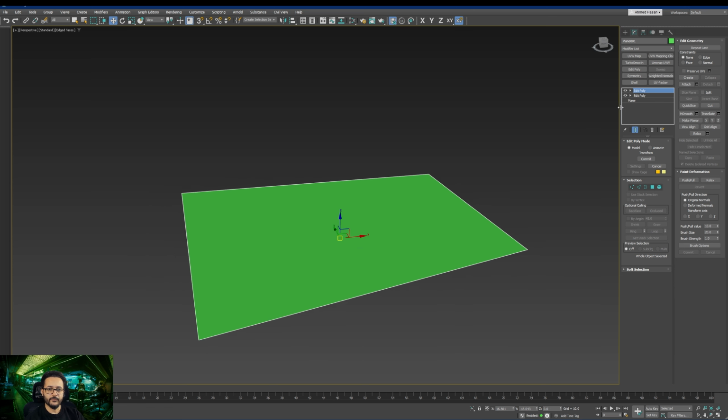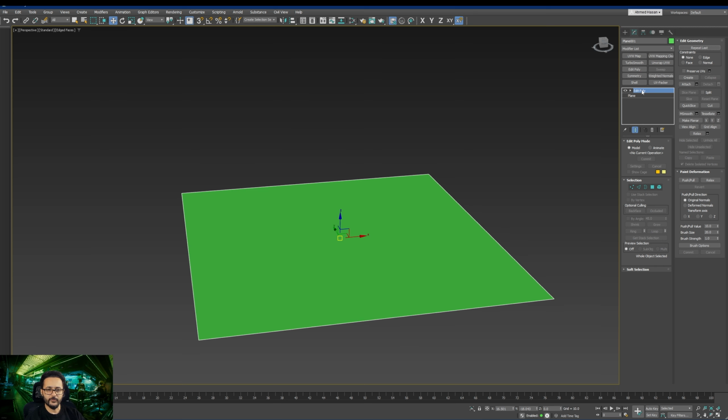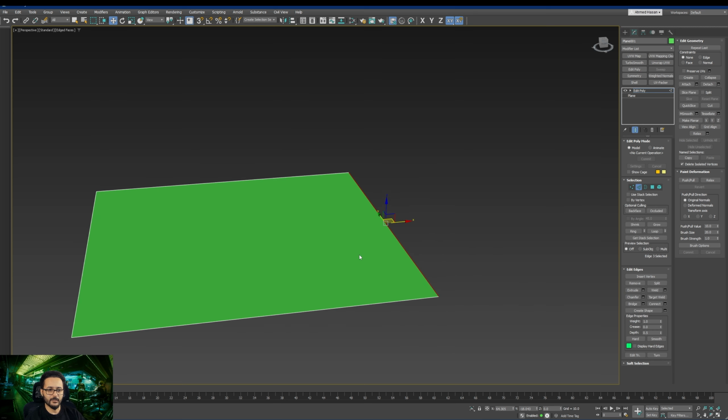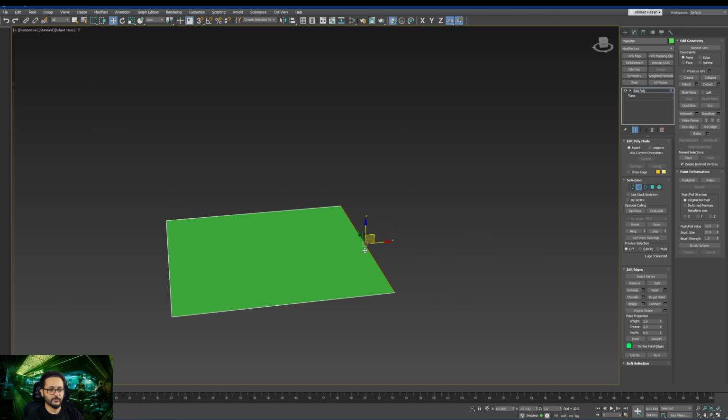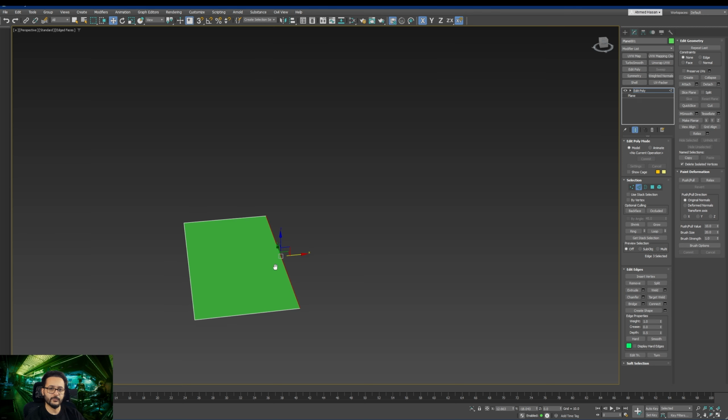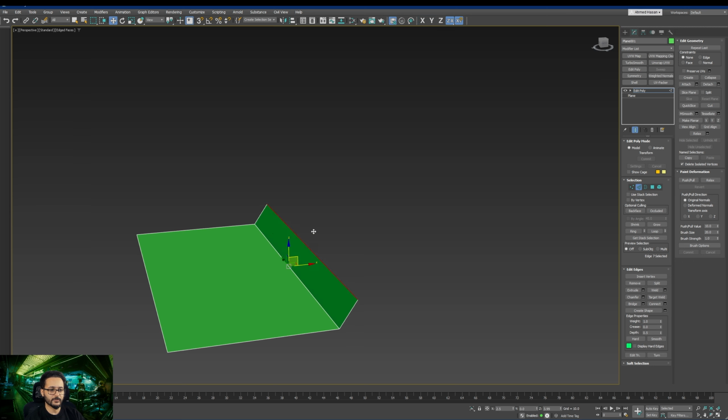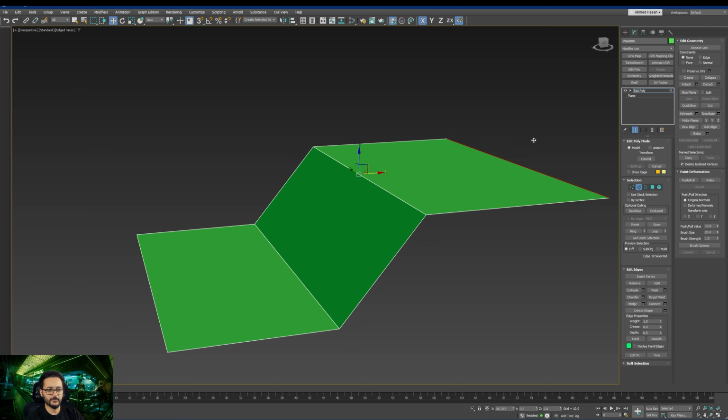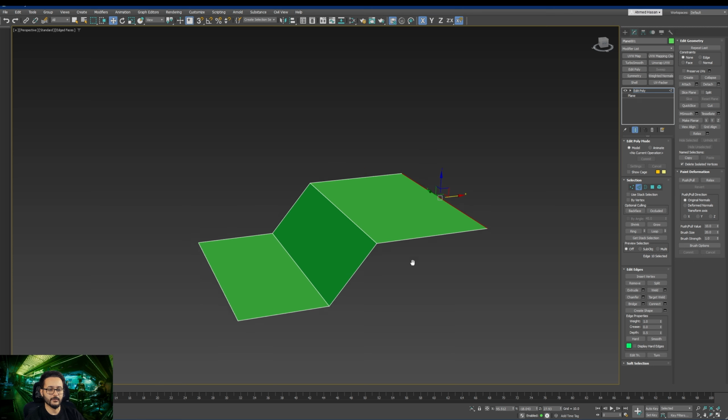Next, the layer stack here, it has priority. Whatever you have first, it will be taken into consideration. If you want to duplicate or make new polygons, you can do so by selecting any edge and then shift, click, drag, shift, click, drag, and there you go.